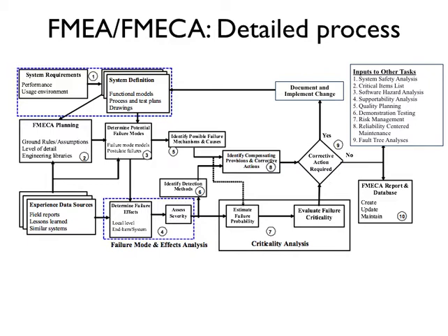So first off, here's a detailed process diagram. This shows 10 different steps for completing either a FMEA or a FMECA. And I'll explain again the differences between those two. But this process that's shown here fits very well with either methodology, and it also fits well to MIL Standard 1629.